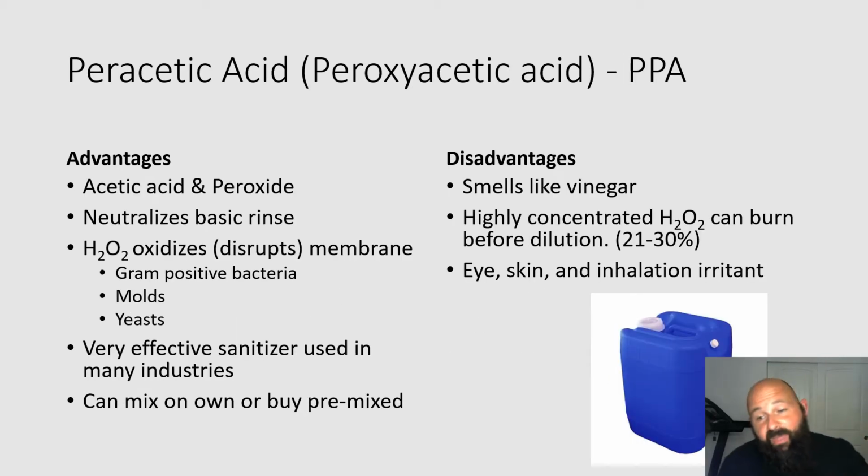All right, now on the other side of that basic cleaner, we can have our acidic sanitizer. So we want to do peracetic acid, and this is something that's really come on strong in the last decade or so. I was hesitant to use it early on because I didn't like the smell of it because it's acetic acid. But a friend of mine, Jake, came out and said, hey, Tim, the reason I love this stuff is I know when I walk in the cellar if my crew is doing the right thing. If it smells like peroxyacetic acid or peracetic acid, it's been cleaned.